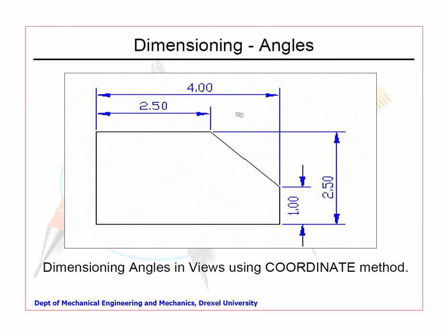This is actually inches, but let me continue to just call it 2.5 millimeters. So, I have 2.5 millimeters, 1 millimeter. This is mentioned and not the other way. You should not write this saying this is 1.5 and this is 1.5. Though while specifying chamfering, we probably specify those dimensions. So, for the remaining part it is easier to measure, check and all that.